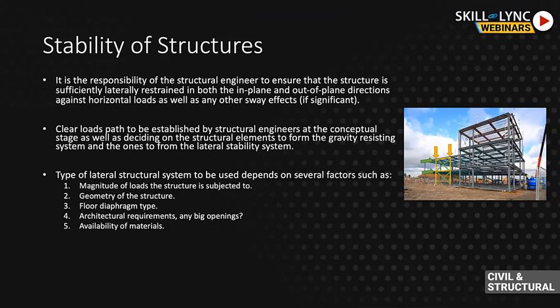The green arrow represent the lateral forces. So these will go into your bracing. In this case, we have an X bracing, tension and/or compression, and then resolved into the other members all the way down to the foundation.